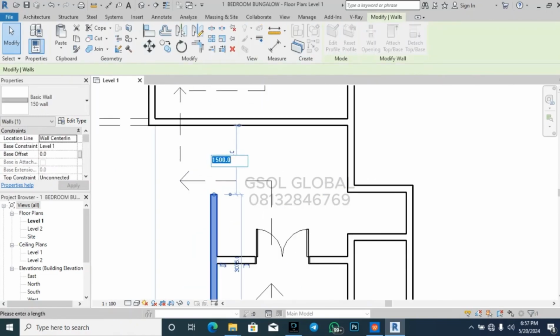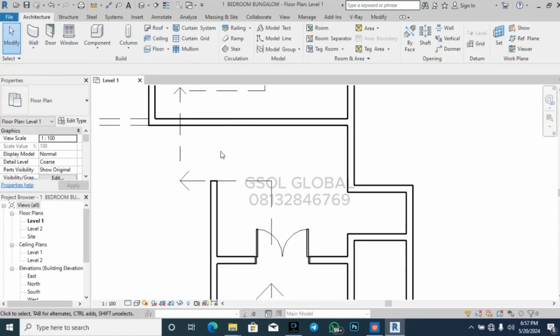So I want 1200 again. All right, so 1200, and then this is the space I'm going to be opening. In this space you will visualize in your mind that we'll be having a beam in this place. But it's an opening and you can't be having block work coming upon a non-structural element. So I'm going to be introducing a beam in this particular place, and the symbol for my beam is to use an annotated line, though we did it here, right?